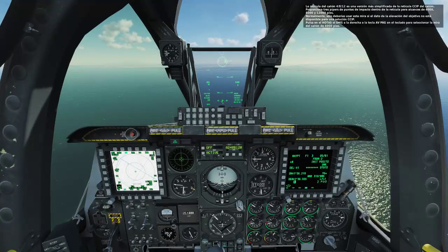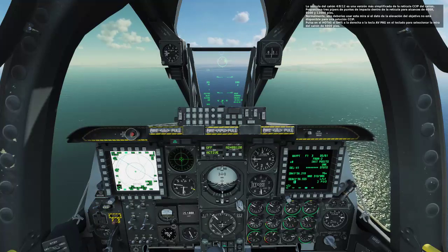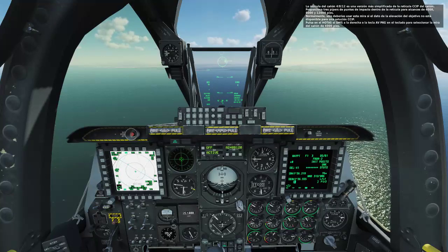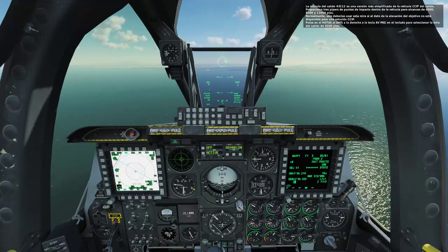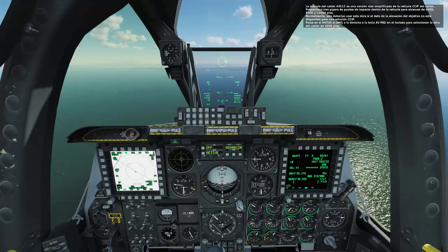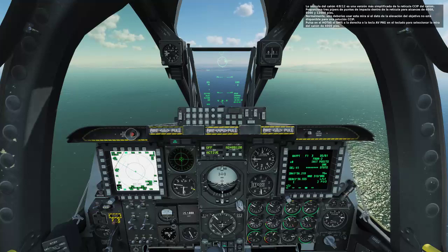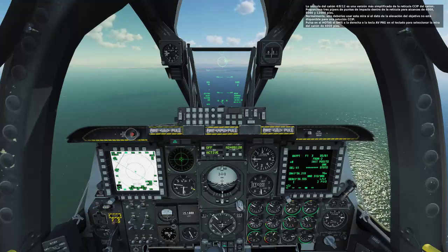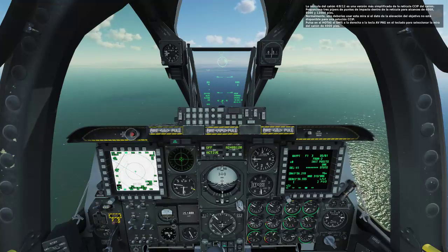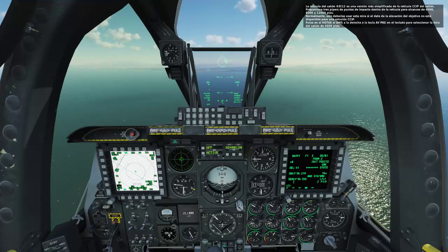The 4A12 gun reticle is a degraded version of the CCIP gun reticle. It provides 3 impact point pippers inside the reticle for the preset ranges of 4,000, 8,000, and 12,000 feet. Normally, you would only use this gun sight if accurate target elevation data was not available for a CCIP solution. Press the HOTAS DMS Right command or page down on the keyboard to select the 4,000 foot gun cross sight.